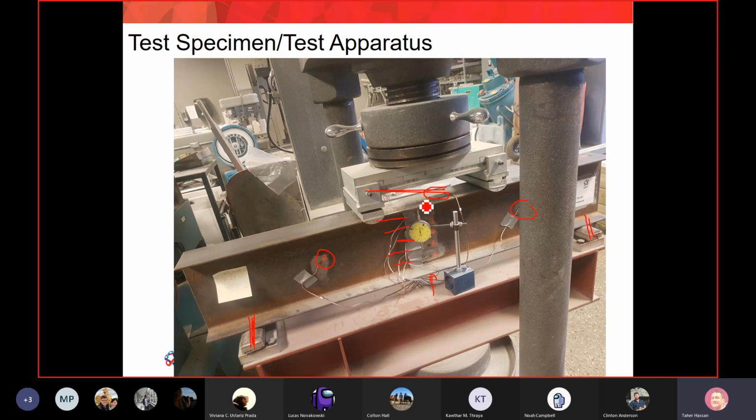You can see, again, 1 is on the extreme fibers in tension. 7 is extreme fibers in compression. 4 is in the middle. 2 and 3 are at different depths. Why am I repeating this again and again? Because this is connected so much to the discussion coming. Every location of the strain gauge will dictate how much strain is in your beam.